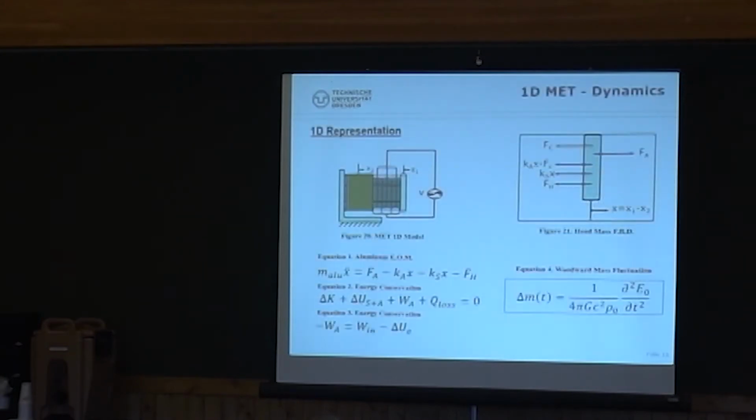But let's see how we can go about thinking about how this mass fluctuation can be generated. This is a free body diagram of the thruster, and I know it's not the right connection to the balance and so on, but I'm focusing on the thruster this time. So you have a brass mass, aluminum mass, piezo stack in between, and these are compressed by steel bolts. If I look at the equation of motion, I cancel the force of compression, because this is basically cancelled by the compression of the actuator pushing on the aluminum cap and the bolts pulling on the aluminum cap,